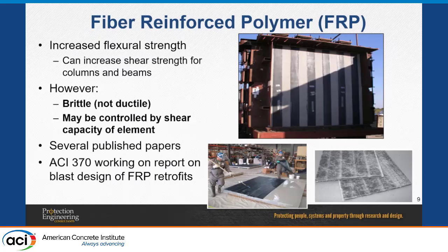Another one, FRP. There are a lot of publications on FRP, and there are a lot of presentations on FRP. And FRP can increase the flexural capacity, the flexural strength of concrete elements or masonry elements. However, there are a couple of things to keep in mind. FRP is very strong, it's very stiff, but it's not ductile. I would say the ductility is very limited. So that's something to keep in mind.